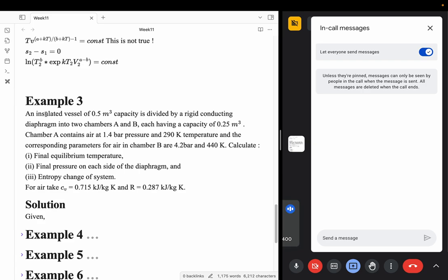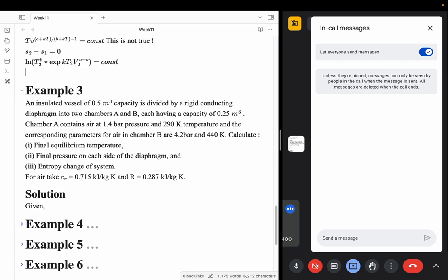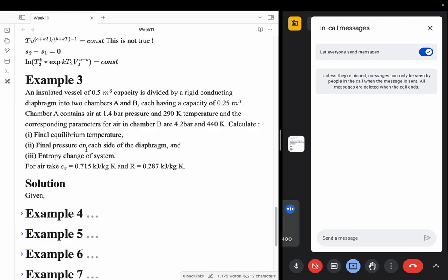First of all, it is an insulated system, so there is no heat exchange with the surroundings. So whatever entropy change happens should happen only within the system, and the question also asks about only the system. So the system is equal to your universe since it is insulated. So the entropy change for your entire universe should be either 0 or greater than or equal to 0. If it is a reversible process, it will be 0. So is this process reversible?